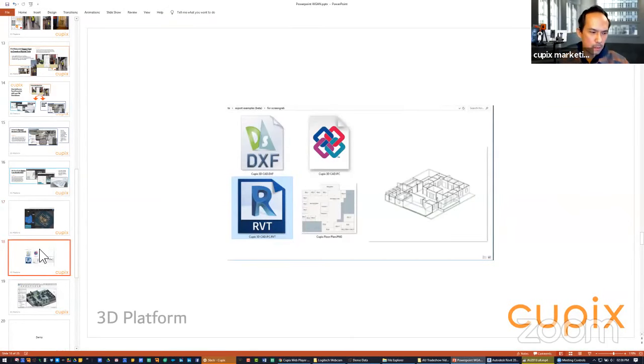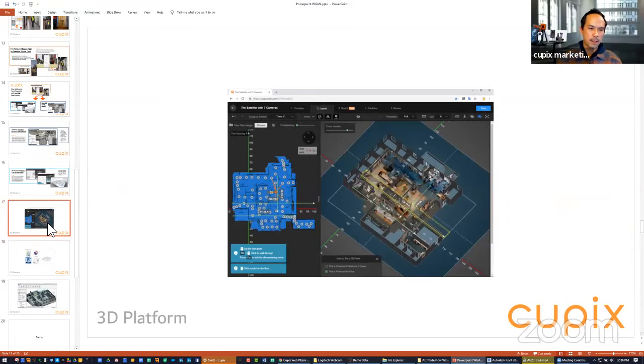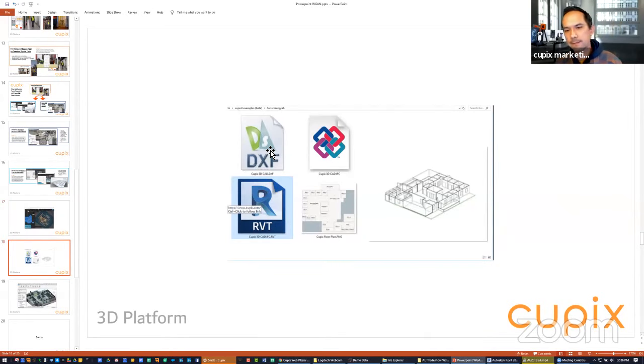These are the formats that you can bring in or extract from this model. This is the CAD model. You can extract DXF. DXF is a common drawing format. Actually, Paul, why don't you go through this? Well, DXF is kind of your common AutoCAD standard for exchange of unintelligent drawings. So you're really just exporting vector information: lines, polylines, circles.